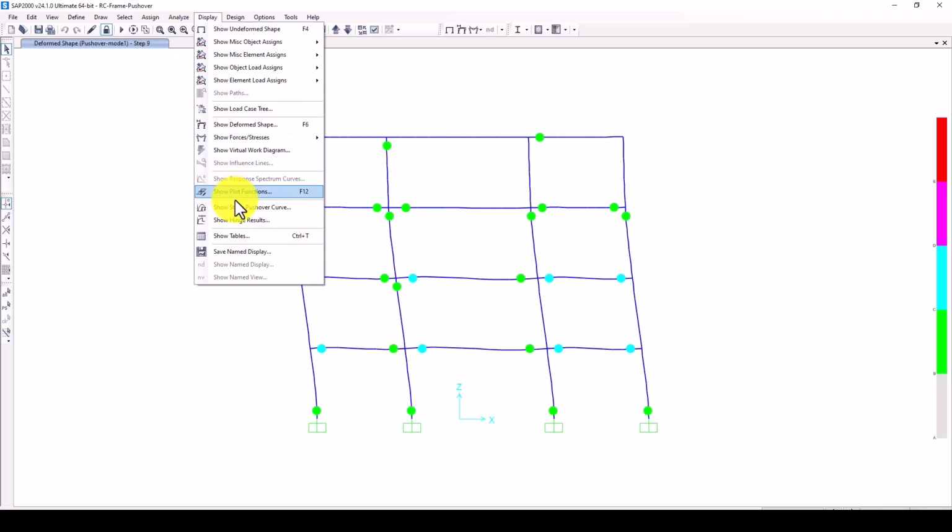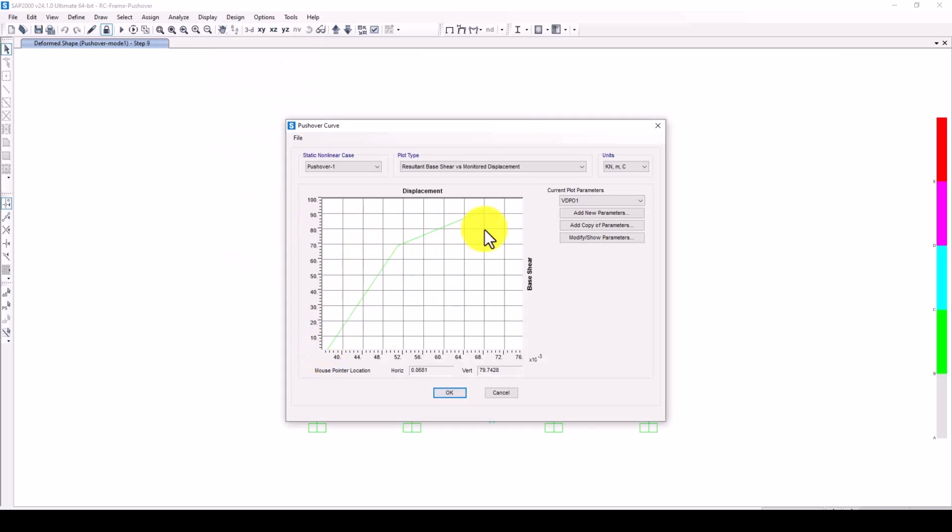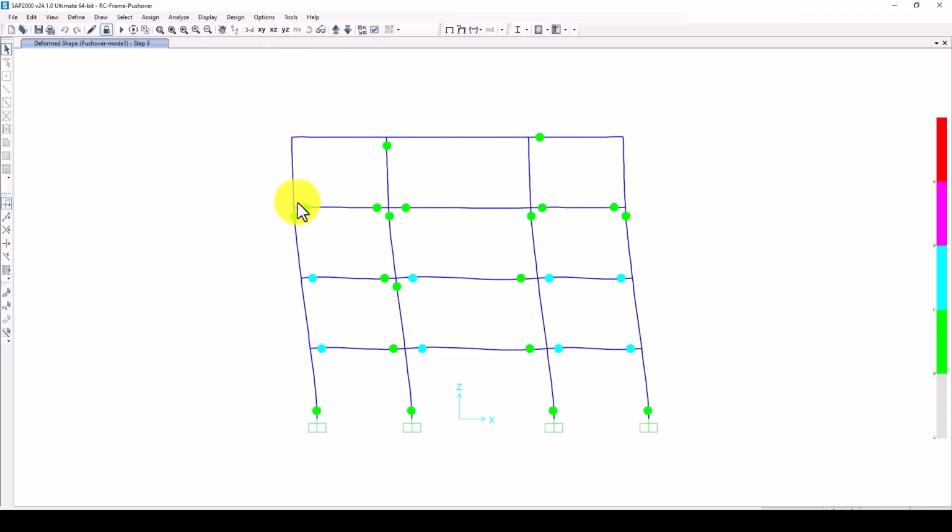and I must go to here because the direction of mode 1 was this direction, so this becomes positive and that becomes negative. Now here is the issue that you see the mode 2 result is not acceptable. So mode 1 is acceptable and it's quite okay. So in some cases we compare mode 2 with mode 1 to evaluate the structure. Mode 1 is the fundamental mode of the structure, so we usually use mode 1, and from that fundamental we take the structure time period and also natural frequency. Now if I unlock and check it with a direct displacement, the result will be 95% the same.